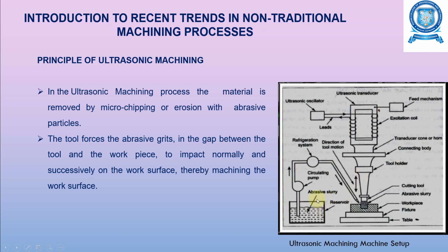And here you have a reservoir with the abrasive slurry, and you have a circulating pump which circulates this abrasive slurry in between the cutting tool and the workpiece, and you have an ultrasonic oscillator here, and this ultrasonic transducer will transduce this reciprocating motion.